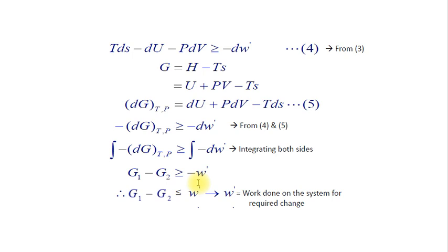So this is the calculation based on thermodynamics of how much work is required for separating out the salt and water from their mixture. This is actually the theoretical work. It is the minimum work, and the actual work will be higher than this based on the efficiency of the pump or the other equipment you are using. There are pressure drops in the pipes and in the flow channels, so that work will be added to this work. This is the minimum theoretical work required for separation.